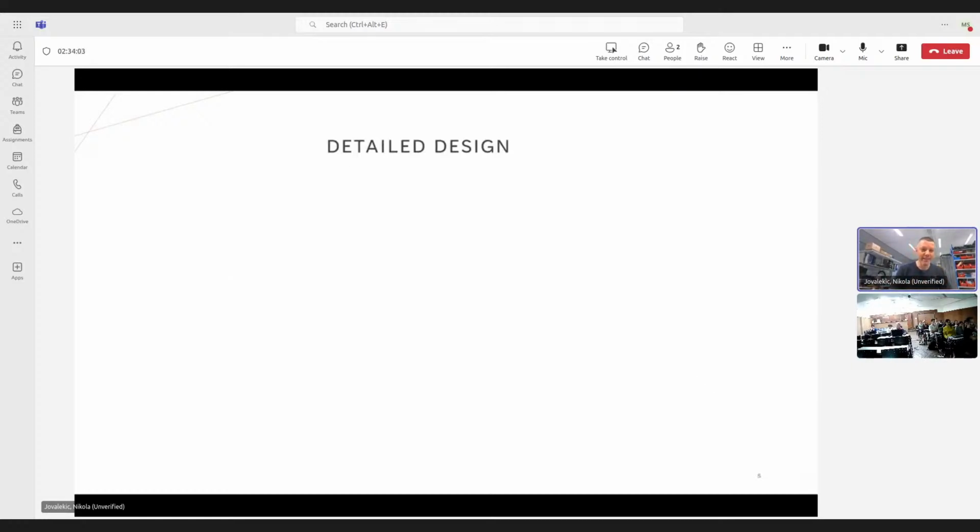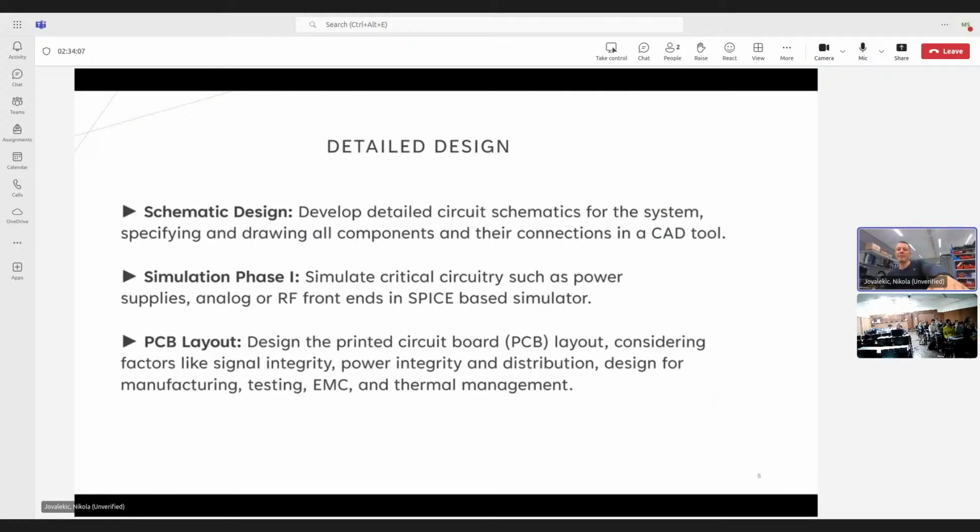That's the first thing. Then you proceed with the schematic design. They finish some initial component placement. They determine the number of layers they need to use. They determine dimensions, if they are not constrained by mechanical constraints from the mechanical team. You finish the schematic, maybe they finish their part. Then you say, okay, now I need to simulate, for example, power supplies. They already started to lay out power supplies. Then you see that some capacitors, some feedback loop is not properly done. Okay, you change the components. Layouters complain a bit, but basically they don't care. They do these changes.